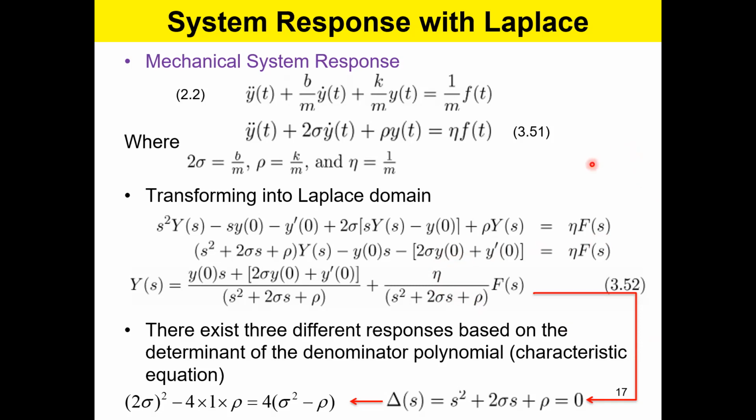Now, for shock absorbers, you definitely do not want an oscillatory response, because if it oscillates, it's very uncomfortable. And you also don't want something very hard, because every time you go over a piece of rock, it's a huge impact on you, and it's again very uncomfortable. You don't want it to be like a solid piece of rock. You want the shock absorber to squeeze, but gently. Not an oscillation, but a simple damping behavior.